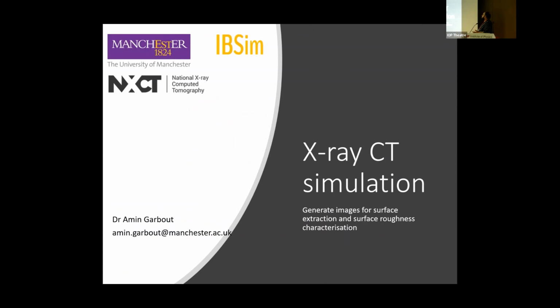So I will be talking about how to use NXCT simulation combined with generating synthetic images of surfaces to extract the surface roughness of AM parts, additively manufactured parts.